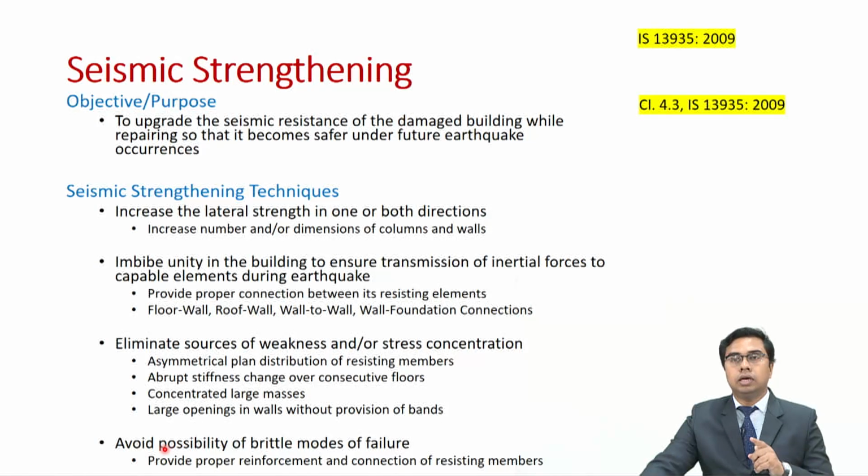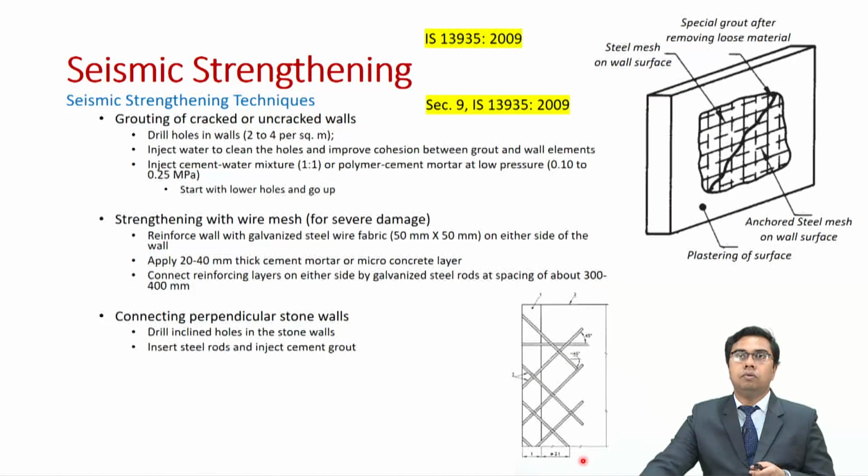We will also avoid possibility of brittle mode of failure. How do we do that? By providing proper reinforcement and connection of resisting members. There are some more techniques to achieve seismic strengthening, such as grouting of cracked or uncracked walls.